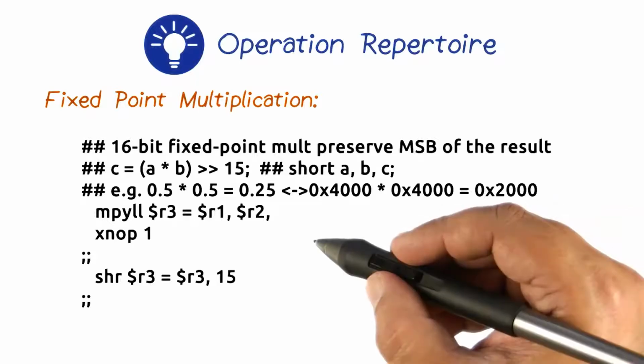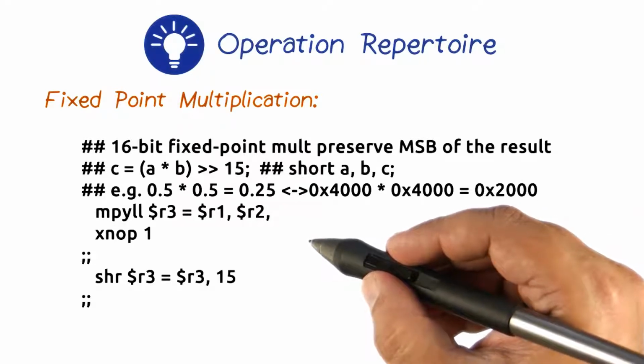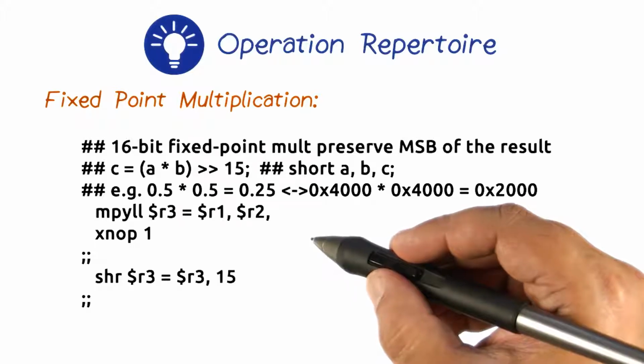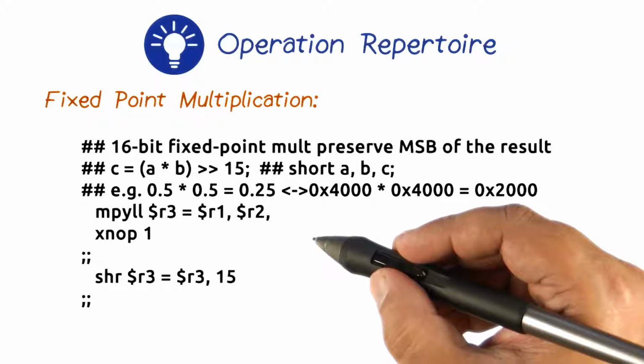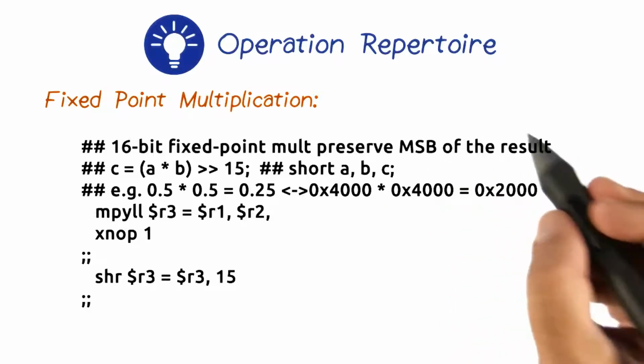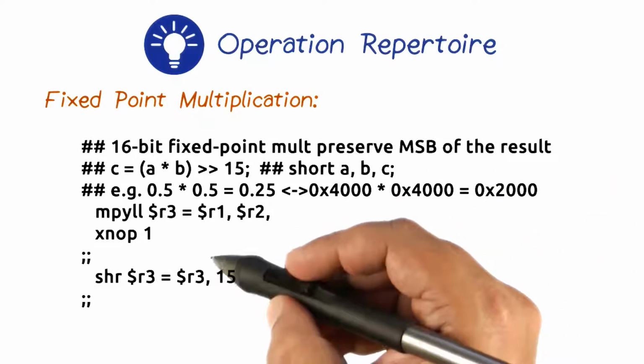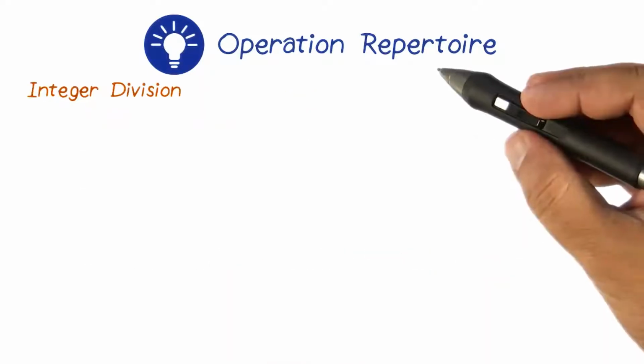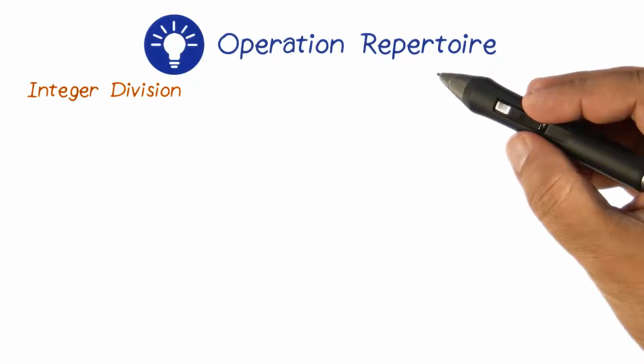So in other words, most of the times we are not interested in the complete highest precision that is available from 16-bit results, because remember, if we multiply two 16-bit operands, the highest precision could be available only when we support 32-bit operands. So the approximation here is we start with 16-bit and we also end up at 16-bit by carrying out these few operations here. If multiplication is expensive, division is even more expensive.